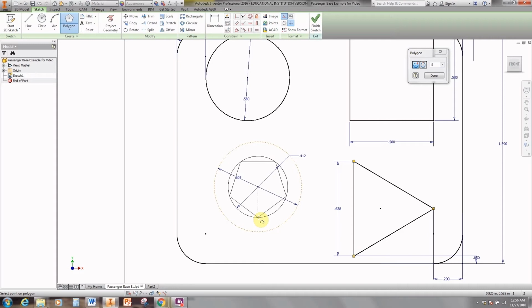So when we go down and hit that first circle, we can see it turn black. That's nice, but that's not where we want it. We want to touch the second circle. And you notice that directly above the cursor, there's a dotted line going to our center point. If I'm off to the right, or off to the left, I don't get the dotted line. But when I'm straight down, now I get the dotted line. That's very important. We need that point to be directly below the center point. And because my outside circle, that construction line, is turned black, I know I'm on that circle, and that's where we're going to put it.